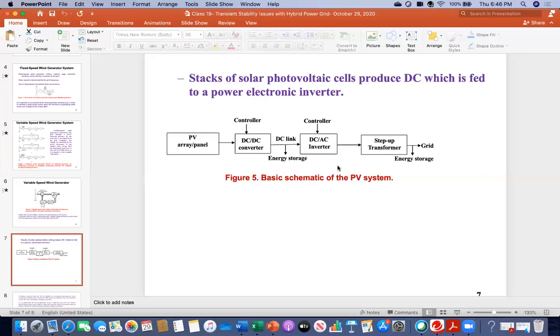Okay, Dr. Ali, therefore your focus will be mainly here. Here you will have all your work, originality and novelty, and it should be bidirectional. Typically, whatever controller you use, if you use a voltage source converter here, then by default it is bidirectional. You just need a smart, intelligent controller. Initially you might try with a conventional PI or PID controller, but later you need to make an intelligent controller.